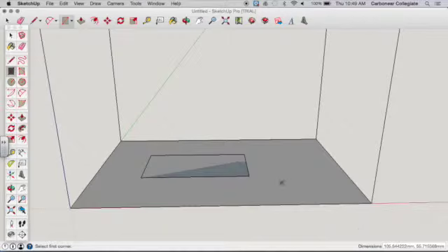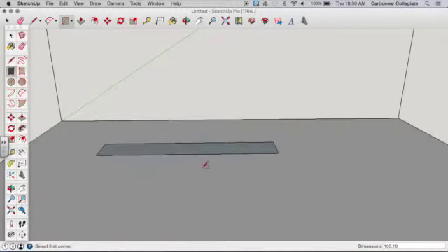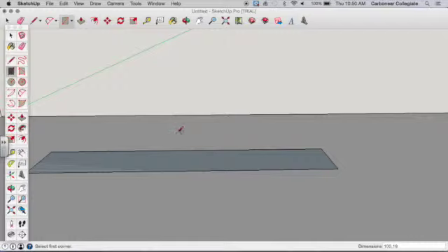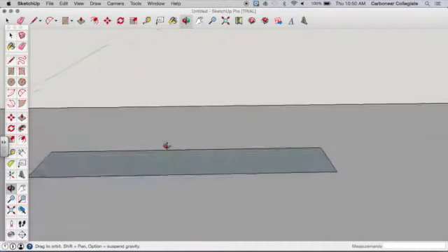To modify these dimensions, simply type in length, comma, width. So the dimensions for our project, as I specified, are 100 millimeters, comma, 18. That will give us our keychain size. So we can scroll in further. Orbit tool, give me more view.